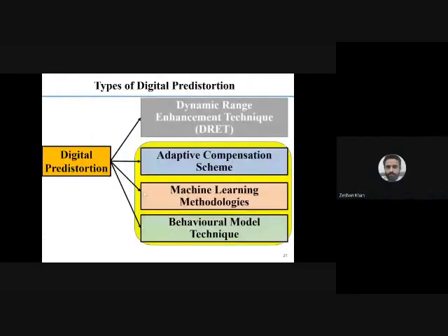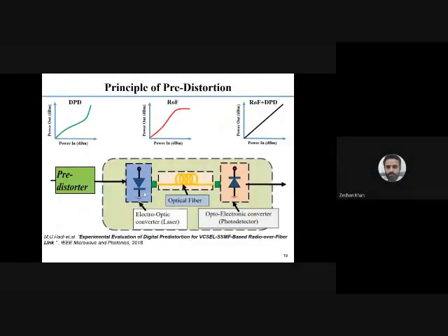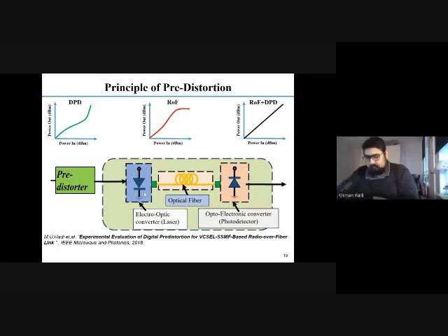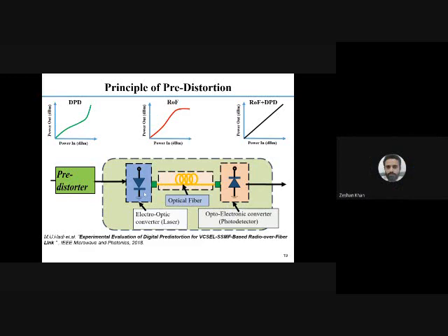Yes, sir. So there are two types of nonlinearities, electrical and optical. And then you are using a pre-distorter that you call DPD to model these nonlinearities. The whole work is focused on modeling this pre-distorter. You explained earlier that you use memory-based techniques like GMP and the memory polynomial technique to model this pre-distorter and to remove the nonlinearities in the system.